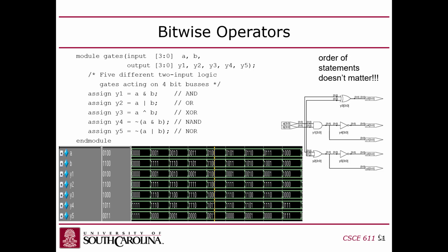You can also do multi-bit signals. The only thing you have to do to extend anything from 1 bit to multiple bits is use this bracket notation. Now this is a little weird. I don't know why Verilog does it this way. There are two things about Verilog multi-bit signals that make it different from an array in Java.